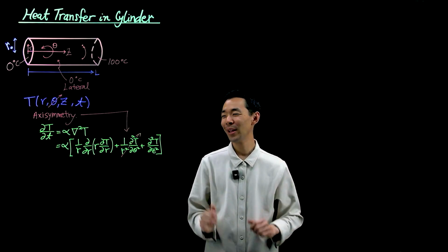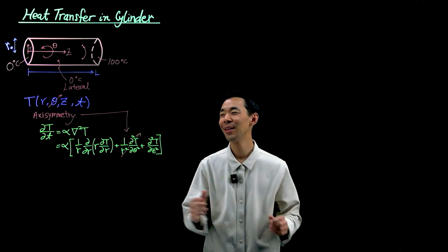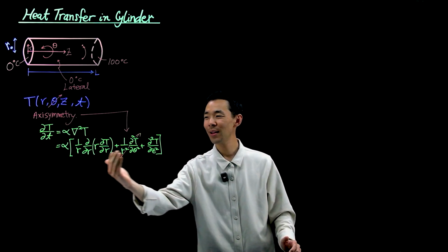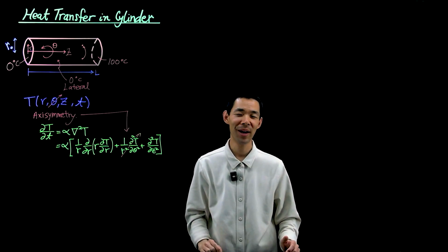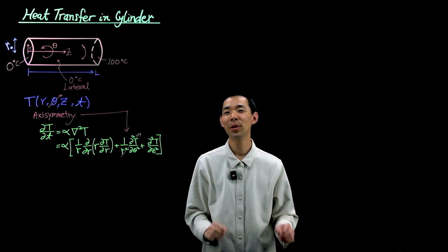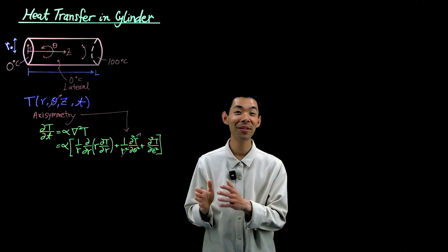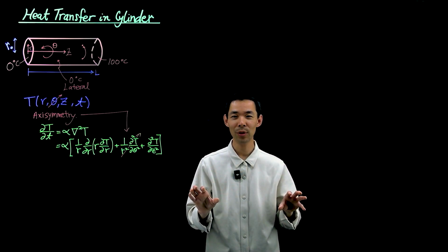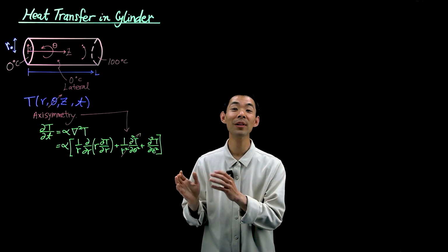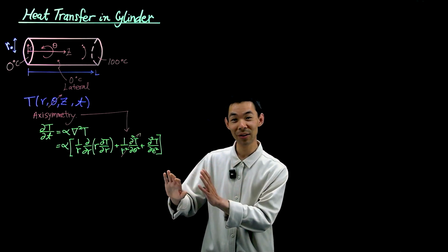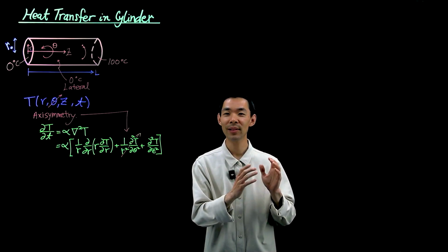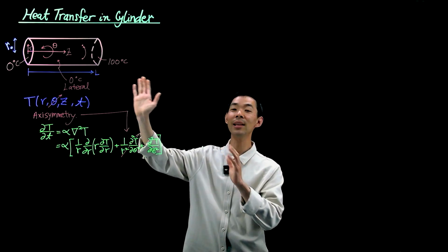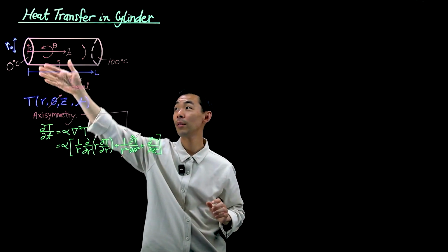Now, we would like to solve this heat equation where we have the transient left-hand side and this Laplacian in r and z on the right-hand side. Just like how we solved the rectangular coordinate system, where we separated the steady-state solution from the transient solution, let's do the same thing here and focus on the transient part later and only focus on the steady-state solution for now.